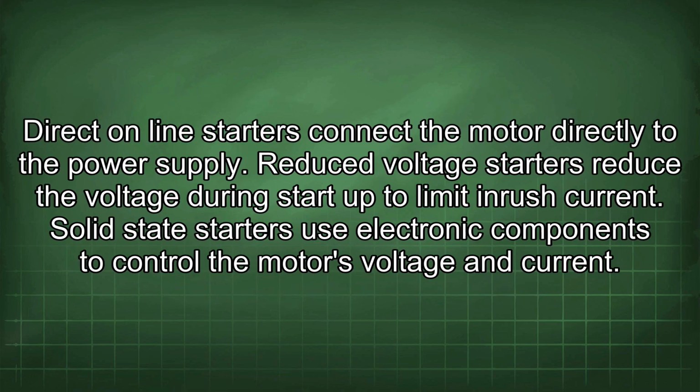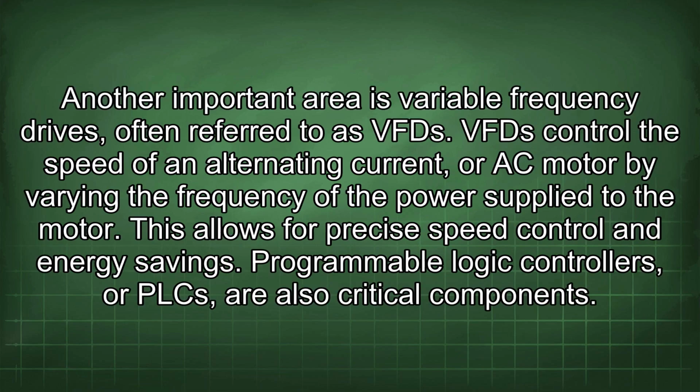Direct online starters connect the motor directly to the power supply. Reduced voltage starters reduce the voltage during start up to limit inrush current. Solid-state starters use electronic components to control the motor's voltage and current. Another important area is variable frequency drives, often referred to as VFD.